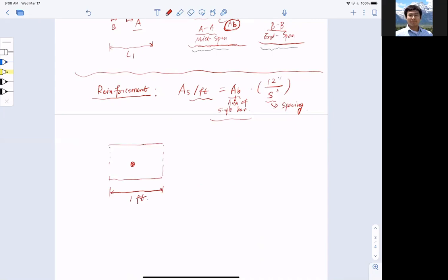All right, and then also you think of it, you actually have a continuous slab in the transverse direction. This is in the L2 direction, by the way. So naturally, you have another bar adjacent to it. And usually what we control is not the bar size. Usually these bar sizes are given, so we have control of the spacing. So on the left-hand side, this is the actual configuration when you put the bars in.